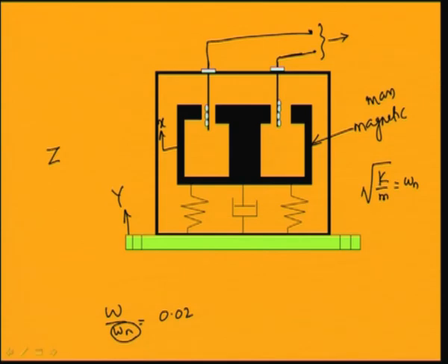design vibration measuring instruments to measure either the acceleration of the system or the displacement of the system. In all cases, when you are measuring the displacement of the system, by differentiating you can find the velocity, and again differentiating you can find the acceleration. Or when you are measuring the acceleration, you can go on integrating to find the displacement of the system. So, now we will